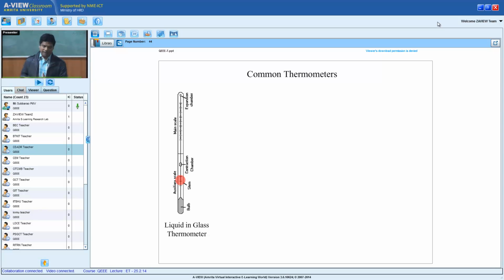Now how do I classify? One such powerful thermophysical effect, which is abundantly ruling the engineering world nowadays, and perhaps you know it, is called the Seebeck effect. Because of the Seebeck effect, people developed thermocouples. What is a thermocouple? You take two dissimilar materials of your choice, or a better choice, and you make a junction between these two, something like this, and you subject it to the temperature. I'm not explaining the thermophysical effect here. Then automatically a DC voltage is developed.